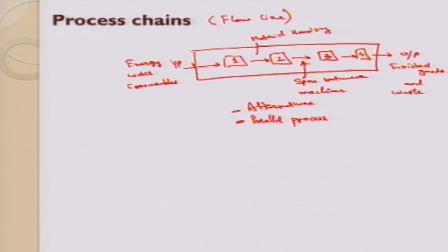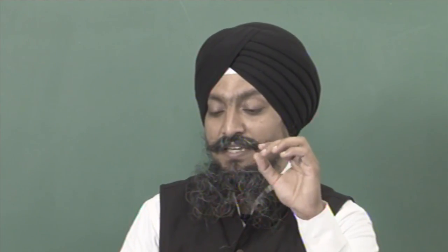So, the green considerations here could be like we have line balancing. We divide the workload to the workers in a way that all the workers are occupied. We can use that concept in energy balancing as well. The power, that is energy that is supplied, which machine is working at which point of time, what is the peak energy one machine is using at that point, and what is the other machine doing. We can synchronize in a way that the overall energy consumption in this line is minimum.